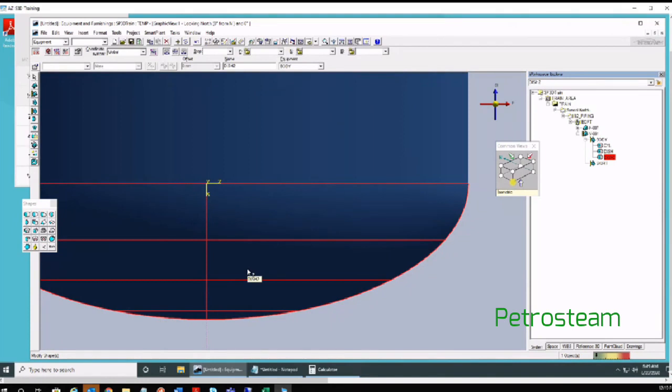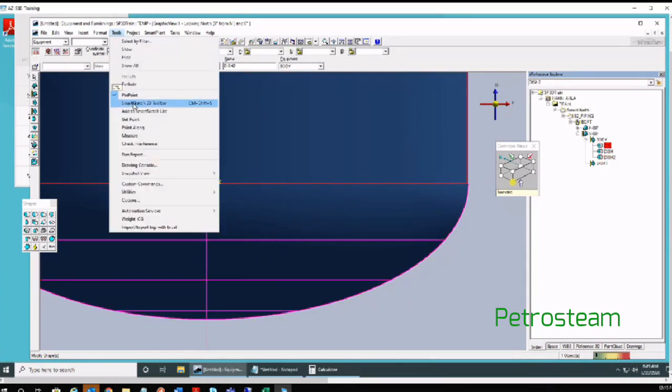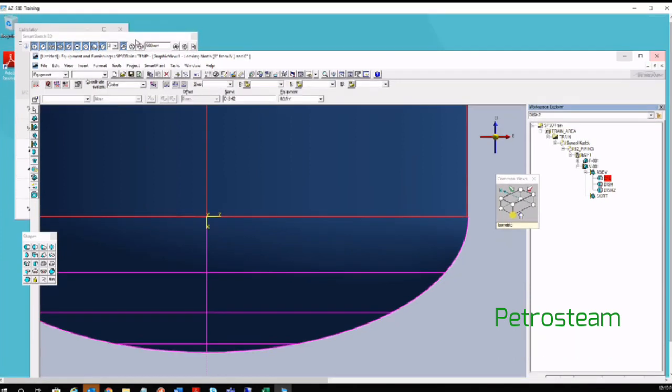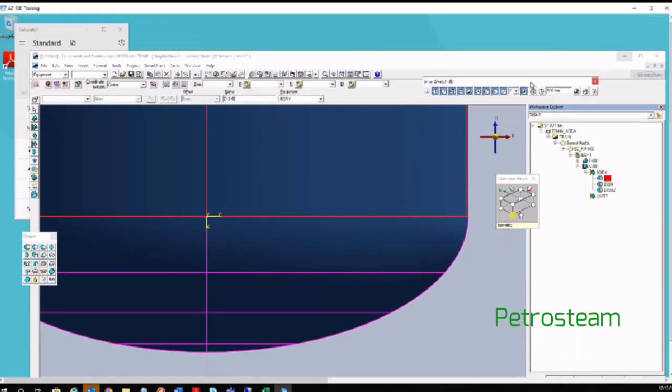Snap point selection is critical here. And for snap points, you can see what is what based on the symbol. See, it is shown as a key point. So at the center there is a key point available. It was showing as a key point, and I selected it when the key point was visible.